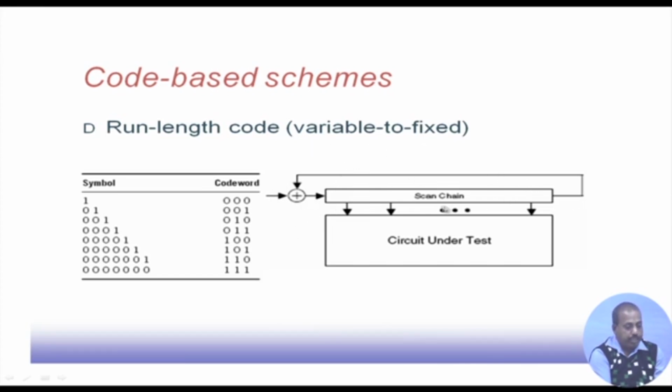By modifying the scan chain architecture slightly, we can increase the number of zeros that we have to shift in from the ATE. So the compression mechanism can take help of that information. Instead of storing the test pattern, we are actually storing the difference, and if the difference has more zeros, which is very much likely, then we may have to shift in fewer bits, because long runs of zeros can be found.